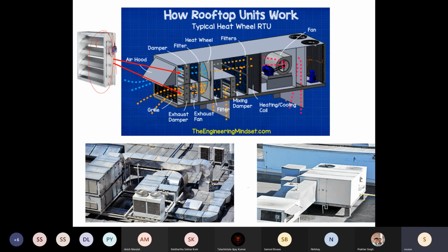Okay, and then supply cold water. So your cooling coil becomes just a cold water supply line. Now this cold water is provided by your refrigeration system. That is exactly what is present in our Nalanda. So the refrigeration system is separately placed on the other side of the road, on the back side.